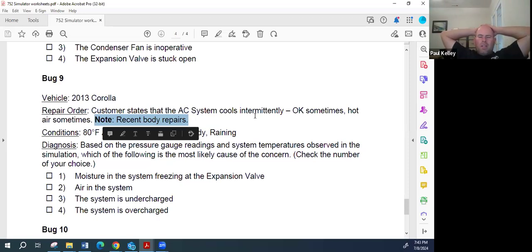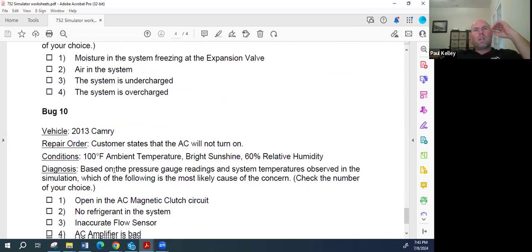Probably realistically, it needs a desiccant bag, receiver dryer, accumulator desiccant, something like that, right? Because that desiccant was sitting there absorbing that moisture all the time, and plus it was raining, it was humid, it was in the south, you know. That system is taking all the moisture it can handle, it's done. And now it's freezing up the needle. Cool, so that was 9.